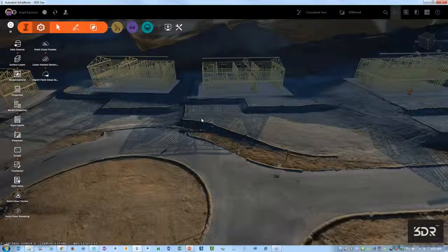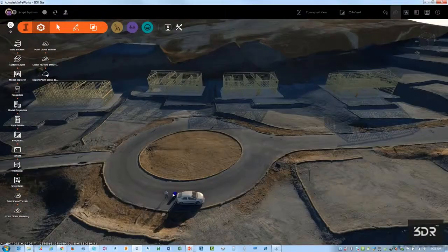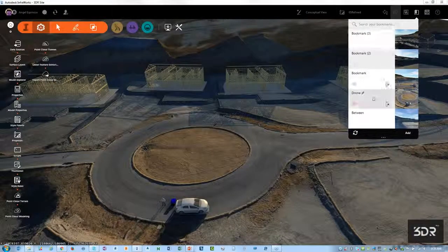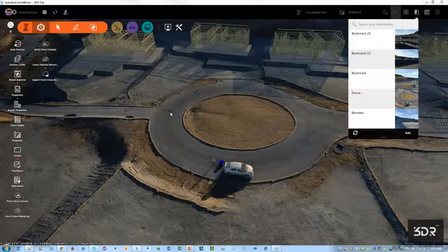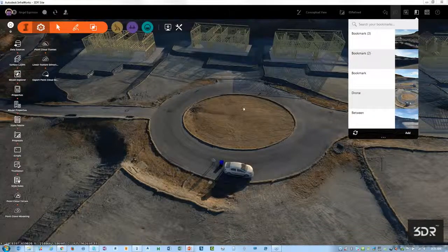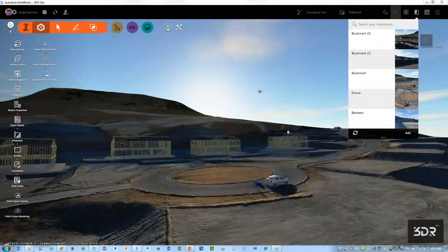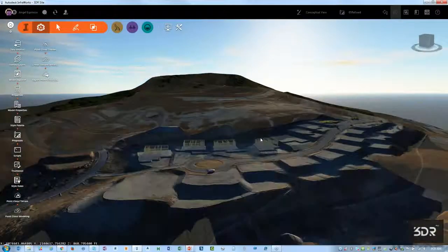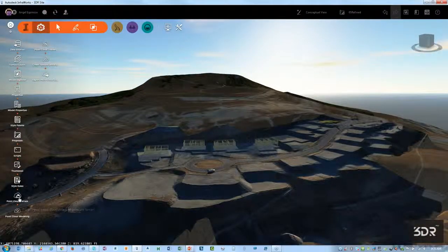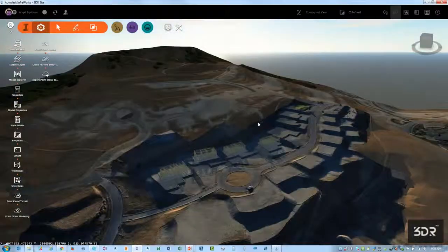And then I'm able to supplement with the intent: we're going to start constructing homes here. If I look through the bookmarks, I can see that this is the drone view. You may be able to make out the drone right there, as I get a slightly different perspective. There's the drone now in the sky. That's what helped us create the point cloud via ReCap, but utilize the capabilities here for point cloud terrain, point cloud modeling, and point cloud theming, to incorporate it into the model and get me to the next stage rather quickly.